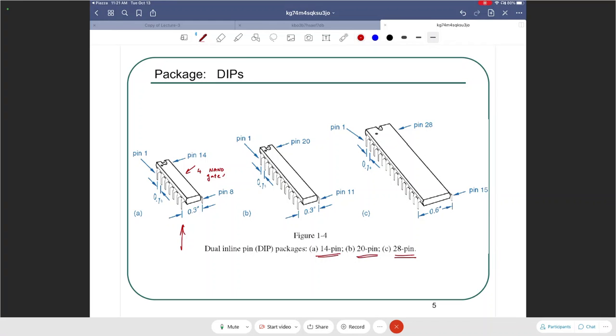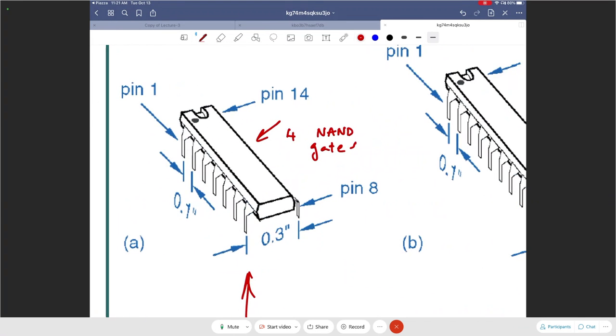What information can you get from here apart from showing the size? The distance between each pin is talked about and all that. But what you really need to know as a user of these ICs is, where is pin 1? Usually there will be a notch, followed by a black dot when you are looking at the IC from the top. That particular dot is actually the pin 1 indicator.